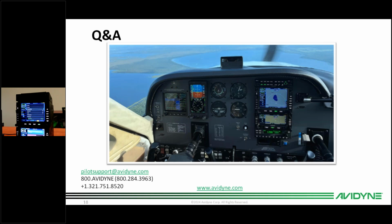The main thing you have to remember is the IFD in the panel and the IFD 100 app, the nav databases have to match. They could both be expired, but they have to match. I mean, for IFR, you want them current, obviously, but if you just want to go fly with them, otherwise you won't be able to transfer the flight plan. You can do all the remote control stuff, but the flight plan will not transfer unless the nav data matches.